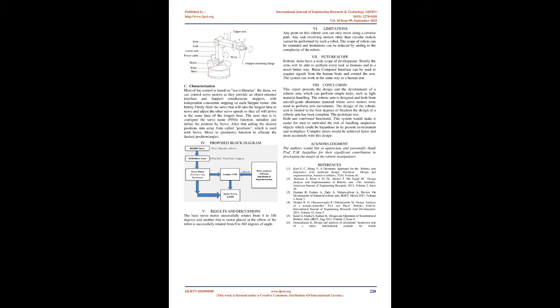The wrist motion consists of 3 motions. Yaw is rotary motion executed about an axis, and causes movement in the right and left directions. Pitch is rotary motion executed about an axis, and causes movement in up and down directions. Roll is rotary motion executed about an axis.